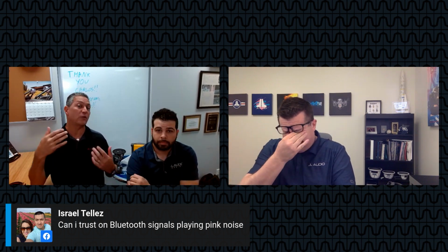If I may just jump in on that, excellent points, one and all. If you take the file that's recorded, that's a full range signal, and you put it onto the thumb drive, and then play it back over Bluetooth, if it looks significantly different at the top end, there's something that's affecting that signal. It's possibly the Bluetooth, it possibly is compression, but it's something different than what it was originally. So if you're trying to fix issues with high frequency roll-off, it may not actually be real. It may be the playback mechanism of the Bluetooth. So in that regard, you may not be able to trust it, but at least you can see it now.